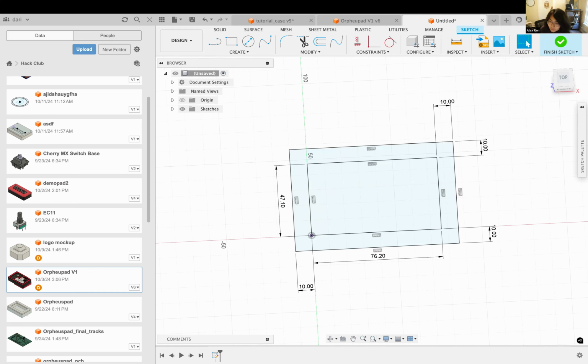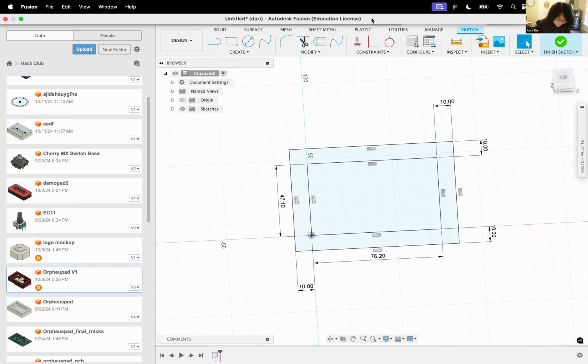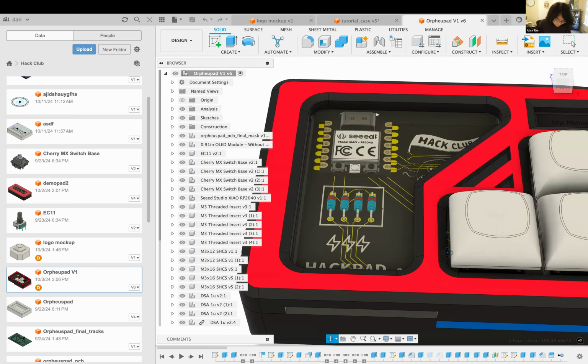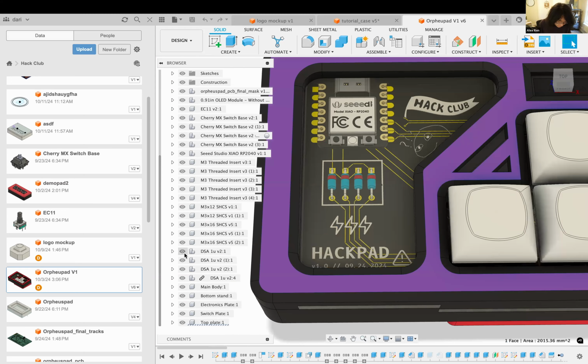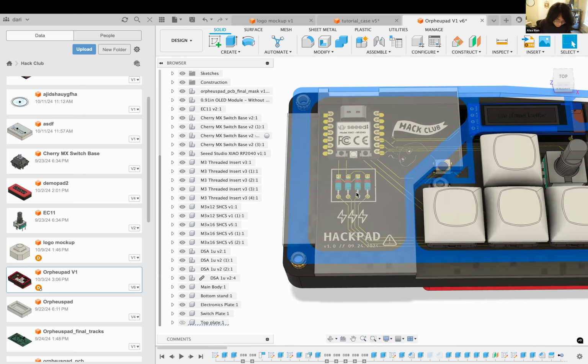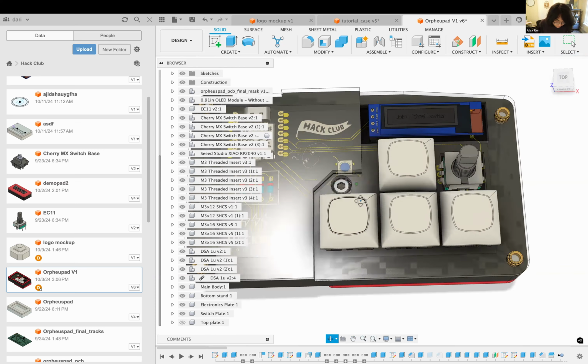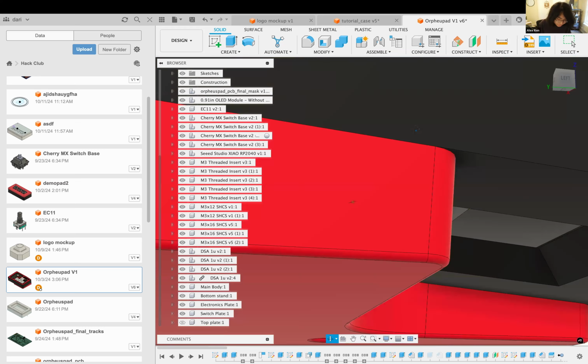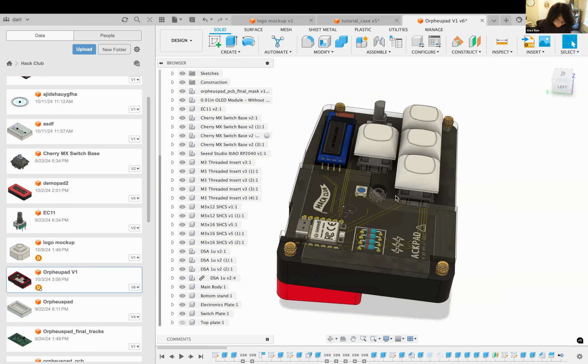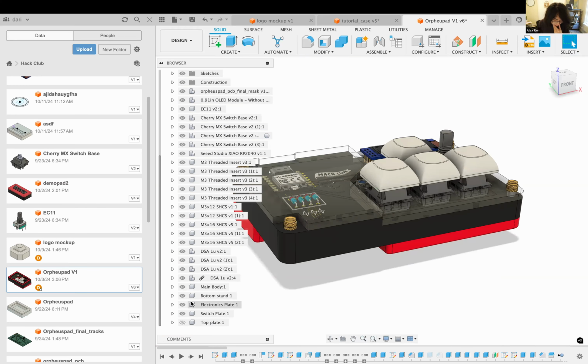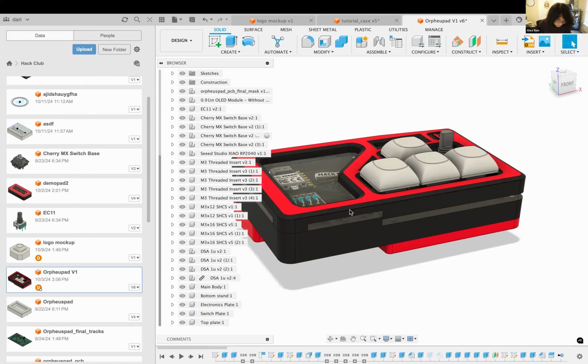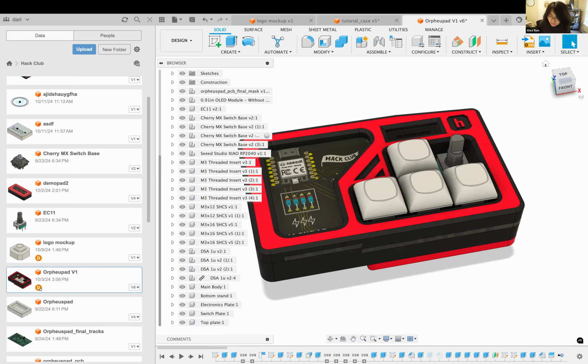Okay. Hello, we should just mounting the PCB. How would you suggest mounting a PCB? Okay, so because we're doing soldered PCBs, I actually suggest just doing a sandwich mount. If you look at, for example, the early version when I was designing this, you can see I put a screw hole for the PCB to screw into the plate, but you don't really need that if you could just have the plate be part of the case. It's a lot easier to model.